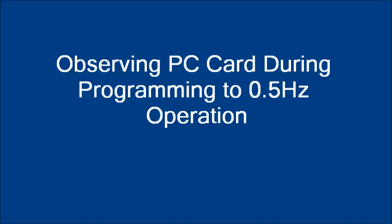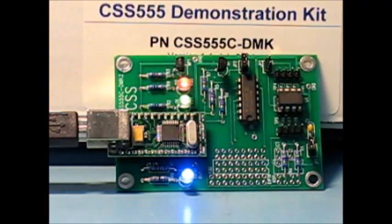If we observe the LEDs when we reprogram from 5 Hz operation to 0.5 Hz, we first see the blue output LED flashing at the original 5 Hz rate. Then as we reprogram and read the memory, the LED flashes indicating each of those steps. Finally, the blue LED flashes at about a 0.5 Hz rate.